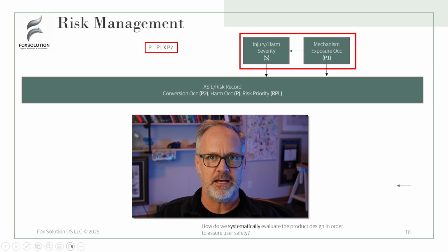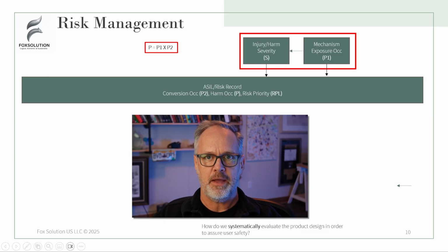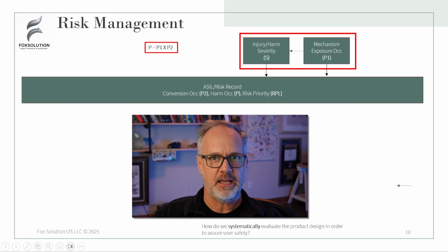We're going to expose that hazard to a user. And if they touch the case, you might have two different harms that could occur. You might have electrocution or you might have shock. You can imagine that when the mechanism occurs, which is shorting the wires and exposing the mains to the case, how often when you touch that case it leads to shock is going to be a different conversion factor than leading to a heart attack.